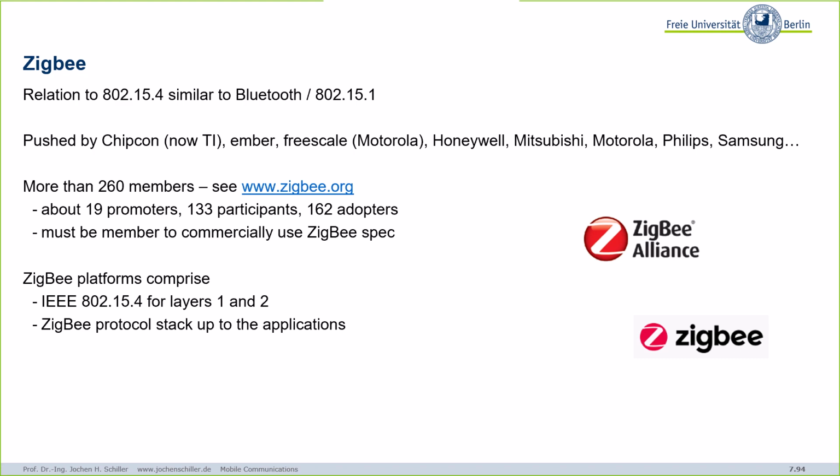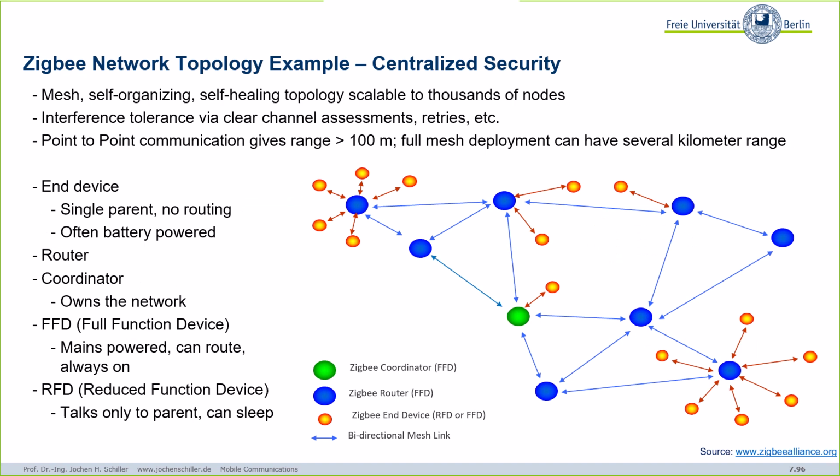So while Bluetooth low energy, etc., is more like a headset to laptop, keyboard, mouse, maybe 10 devices, maybe 2 devices, maybe a spontaneous transmission of a beacon, Zigbee is different. They want to support many devices, very simple devices called reduced function devices, and they could be a sensor, and this sensor could detect a fire, for example, and that's it, and then signals the fire to a parent node.